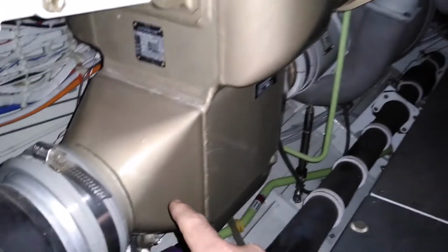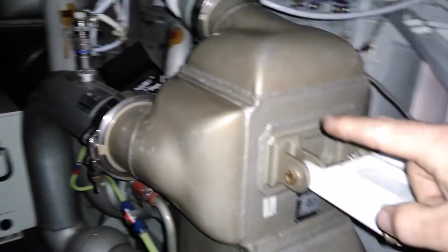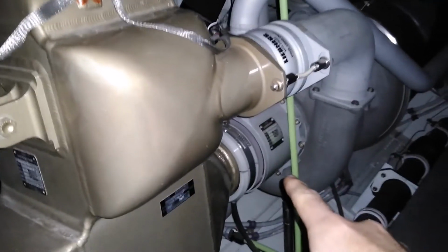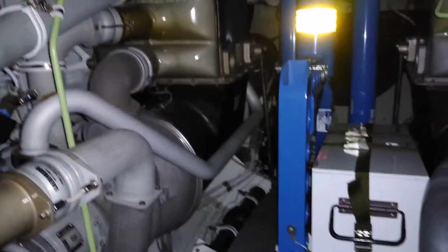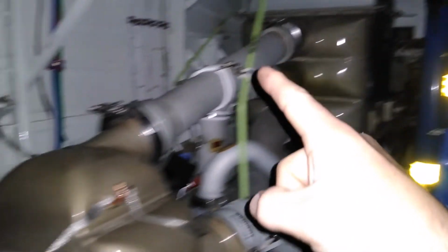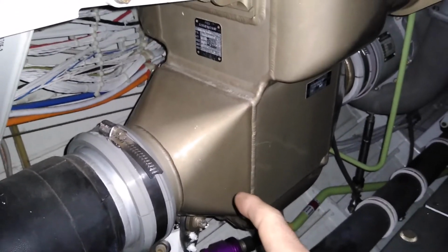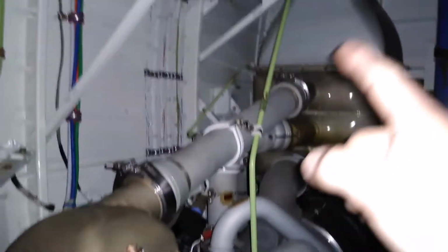After the air goes through these heat exchangers, it's dried up, and it comes back through here. Once we come back over here, it puts us on this side, which we can see over here. And now it gets piped into the inlet of the turbine. So up to here, we have bleed air that was cooled off, compressed, cooled off again, then brought over here to cool it even more, to drain the moisture out of it. The water gets collected, it gets sprayed over there, and then dumped out the back.